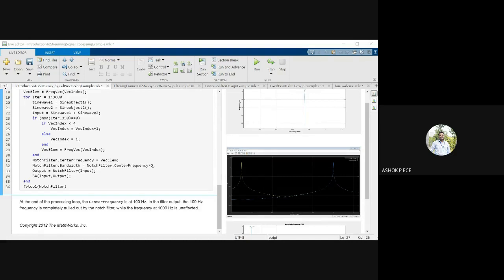You can see the frequency. See this portion. As I move, you see this portion changing, right? So you have two cursors. You can move the cursor and see what the value is. And this one is channel measurement. You can see the channel power, the occupied bandwidth, the frequency error. You can see everything here. Everything is shown to you.